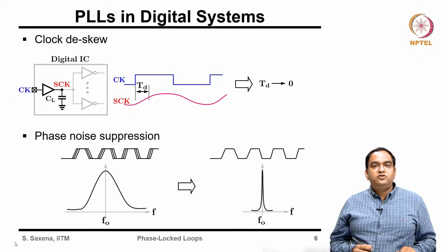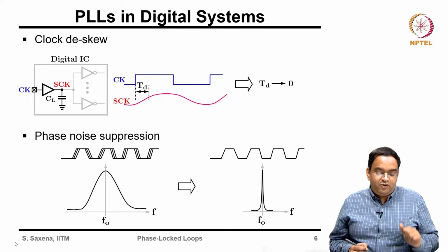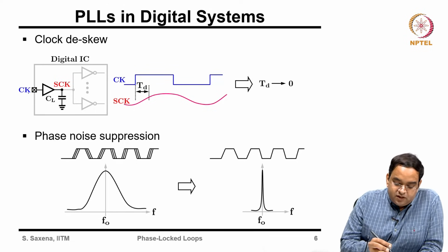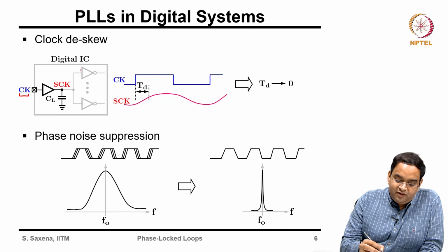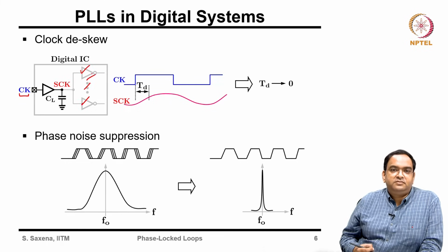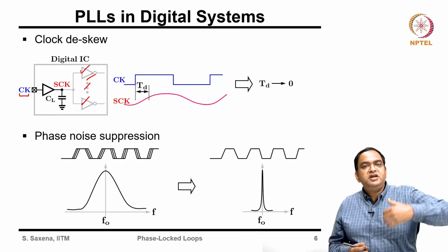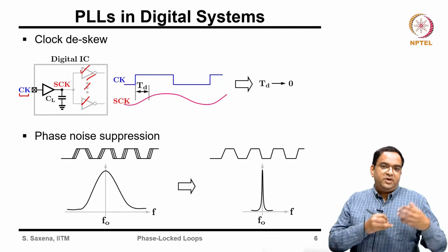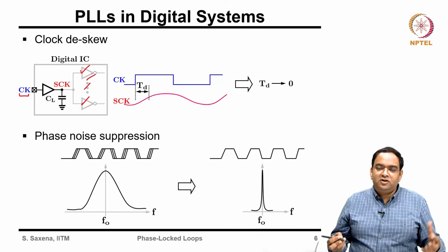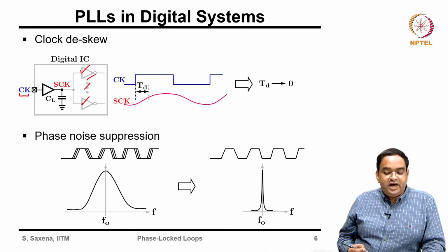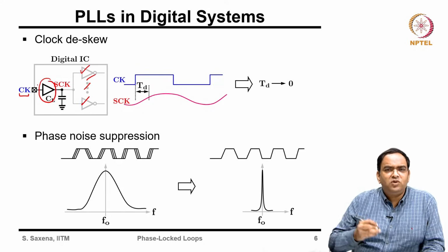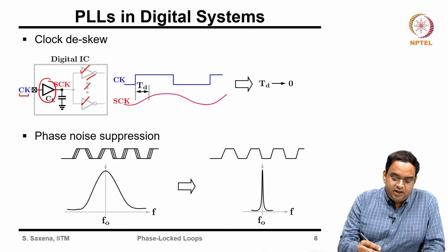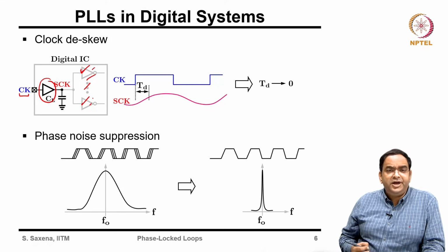Next, you see the use of PLL in digital systems. Okay. So, here you have an input clock which is a periodic signal and you have to drive a lot of gates. See, the clock may feed through multiple blocks, maybe flip flops, inverters, logic gates or something else. So, when you are using one single block, no matter how large it is, you may have to drive even a much larger load, as shown by just inverters here.